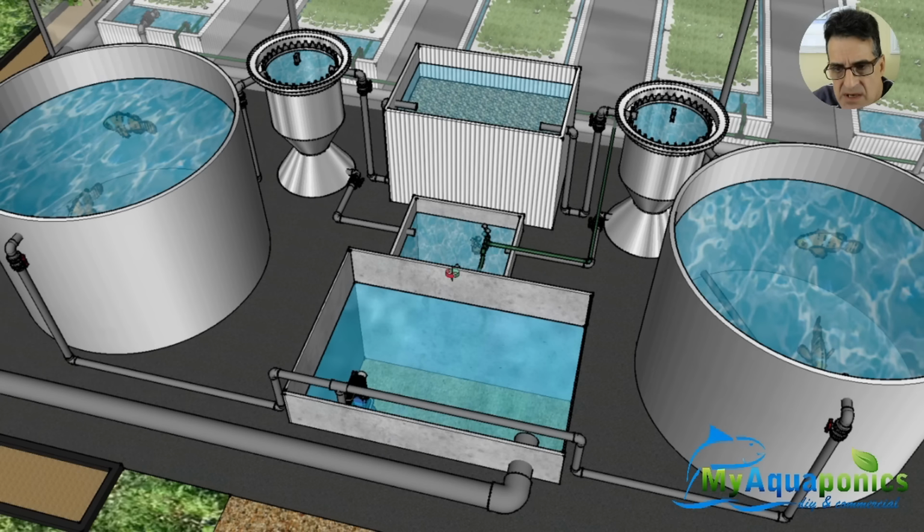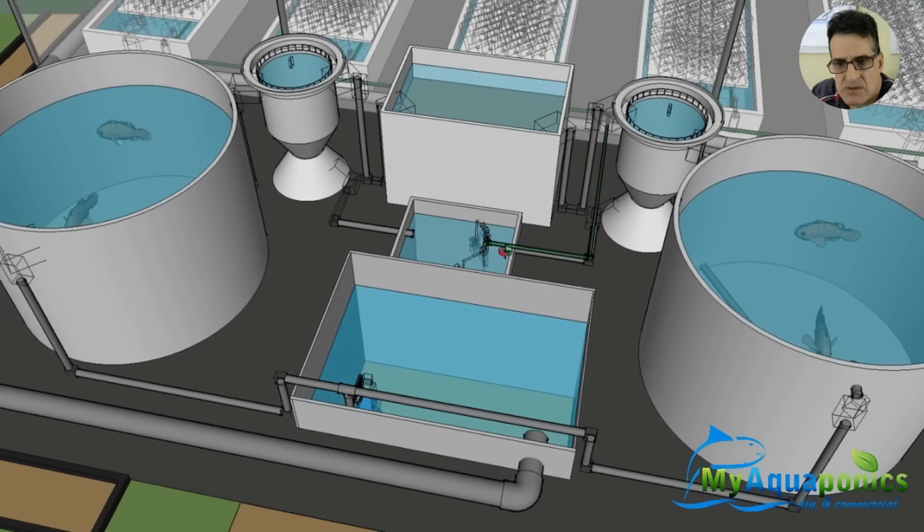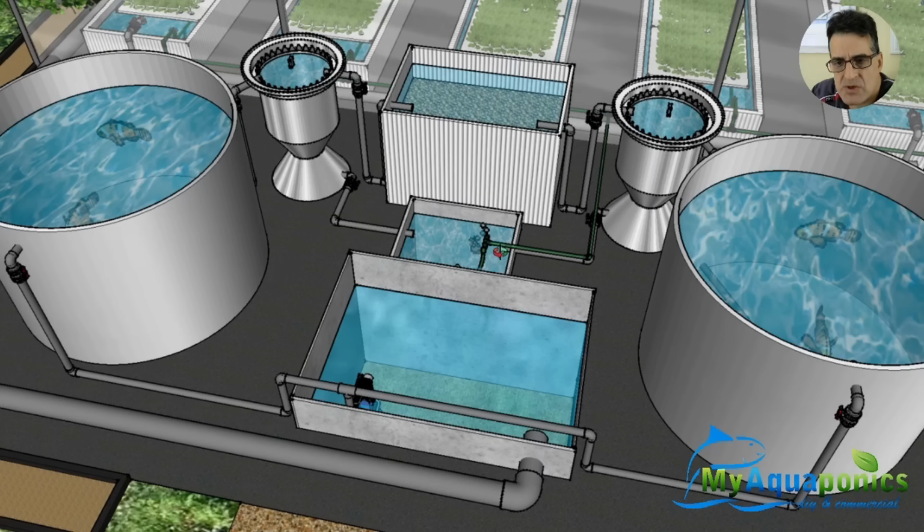This mineralizer tank is isolated from everything else, and with heterotrophic bacteria and aeration in this tank, the heterotrophic bacteria proliferate and they'll get rid of any solids. So uneaten fish food, proteins, carbohydrates, all that gets turned into ammonia and minerals, which you can then reuse in your system. So you can call the heterotrophic bacteria the decomposers of the bioworld.